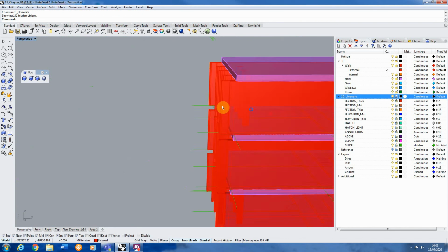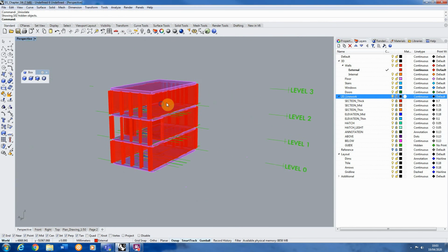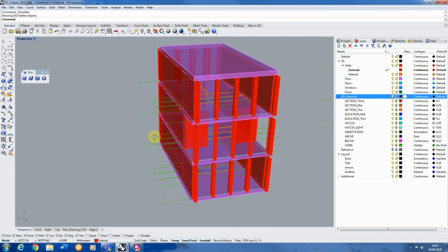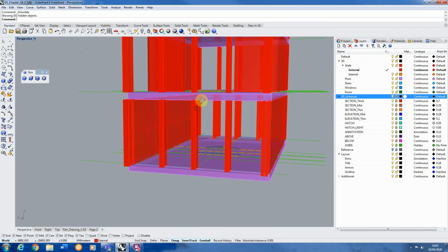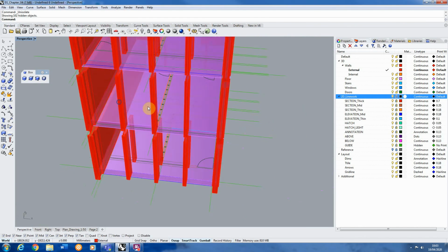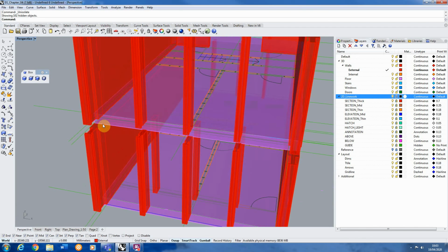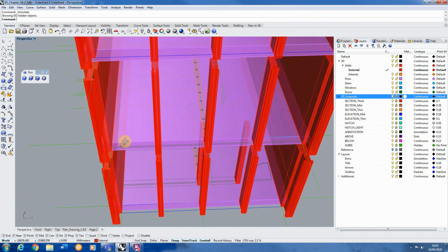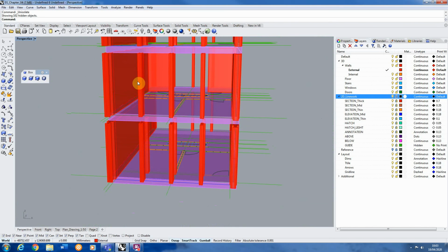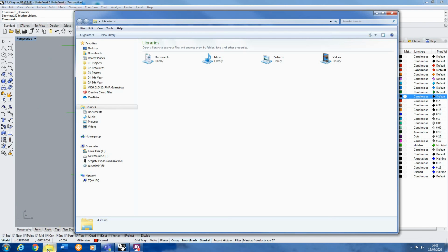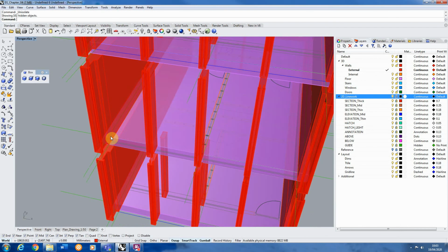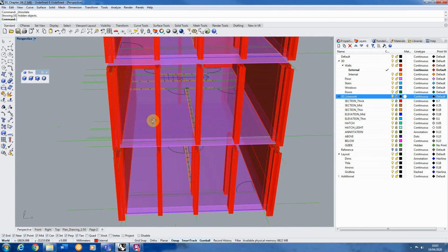So now you can see that I've extruded out these external walls, and we're starting to get something that resembles our 3D model, with simple walls extruded and our floor plates in place. Now obviously when you extrude, for these back windows here, we actually want windows in place, and at the moment we've just got these strip walls. Our windows on this plan aren't full height like this, they actually have a window sill which goes up to about this level here. So we're going to need to model that in and add it onto our extruded walls here.